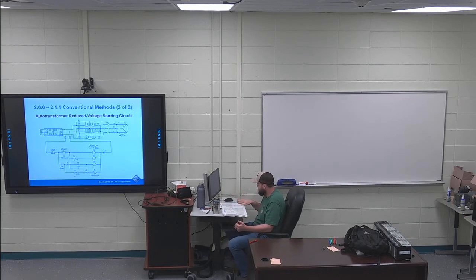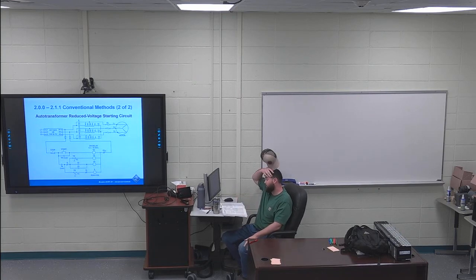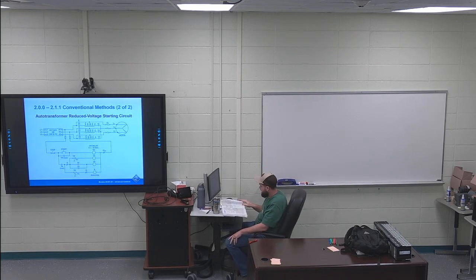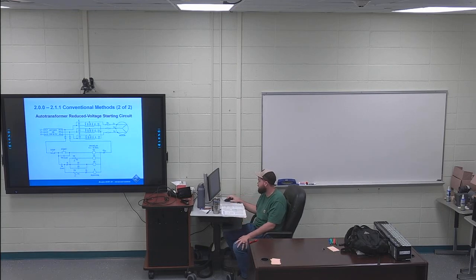The last paragraph on page 15 through the end of that section is highlighted. I'm going to read through this, but you pretty much need to know how this circuit is going to work. I'm going to try to read through this slowly while pointing at this stuff as I go. So pressing the start button energizes the timing relay. This causes 2 sets of normally open instantaneous contacts to close.